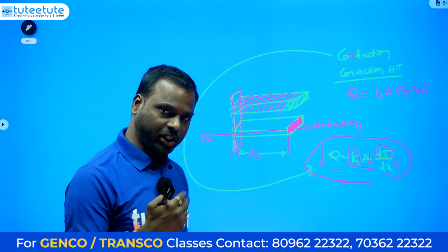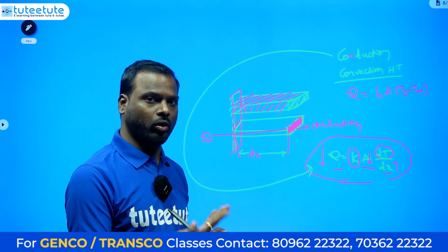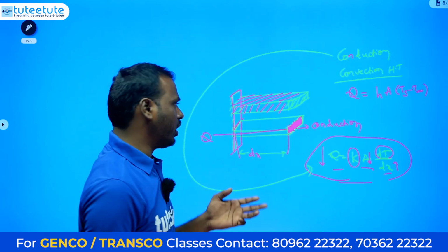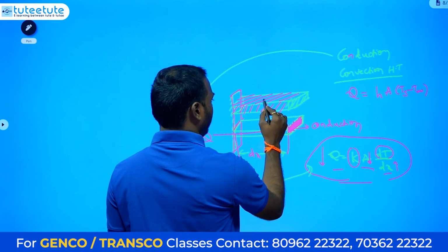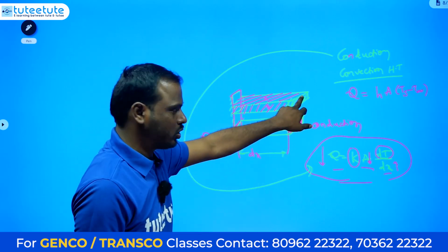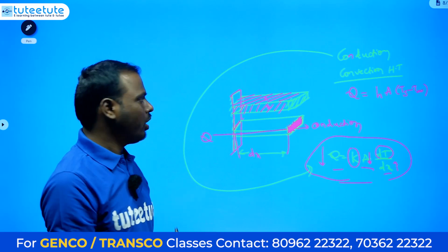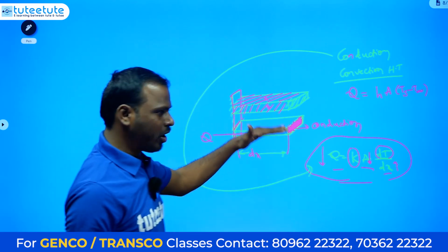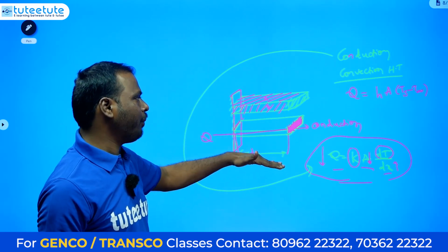because conduction takes place within the solids, but convection takes place with the fluids, generally the fluid as well as the material, I mean the solid. So here this is one area, this is another area, and the opposite sides will be other areas. The total area attached to the atmosphere is the total area we are going to consider. It is very large because of the number of plates, or the fins. So what happens to the area?